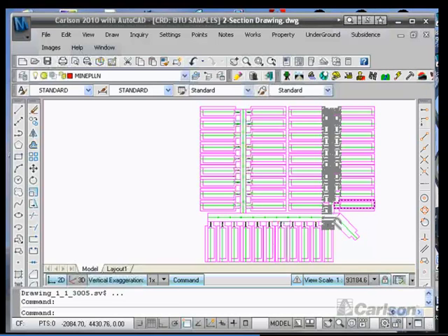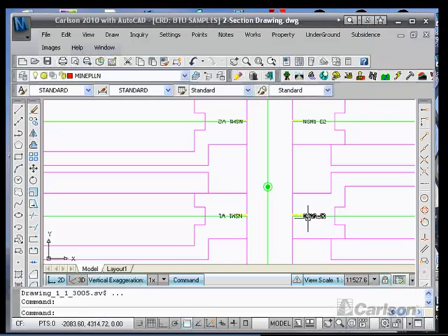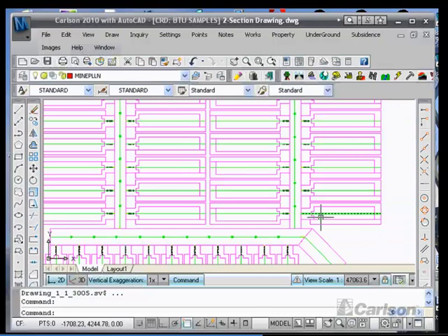If I pick on here, I can show you that the mine was laid out using the auto place panel by text, but then we had two boundaries, in this case for perimeters. This perimeter was used on each section for advanced mining with a separate extraction ratio from this panel, where we had a combination of driving rooms on the right hand side and then recovering pillars in the center of the panel. In doing so, we would schedule this to drive up on that outline and back on this one, and did that for each panel.